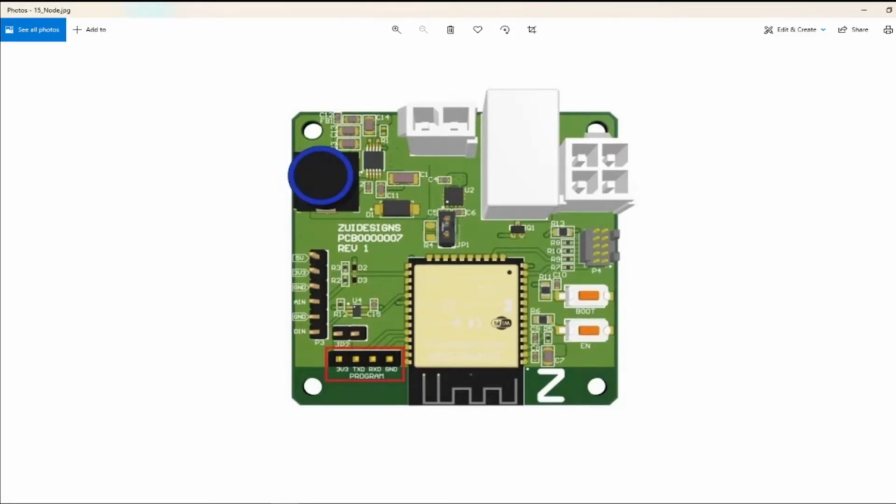The 4-pin program header provides the serial interface used to flash new software to the ESP32 module and observe runtime information through a computer terminal. A 10-pin JTAG interface along the right edge of the board provides a method for testing and debugging the node circuit boards after the manufacturing process. And finally, the two push-button switches on the right side of the board are used for resetting the ESP32 module into either a normal operation mode or into a programming mode for applying new software.